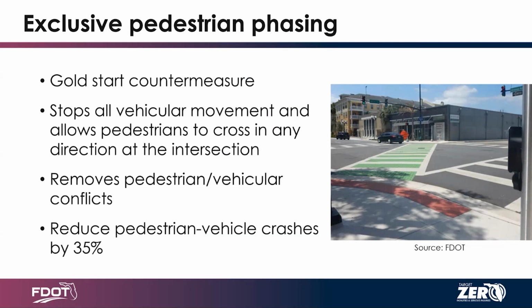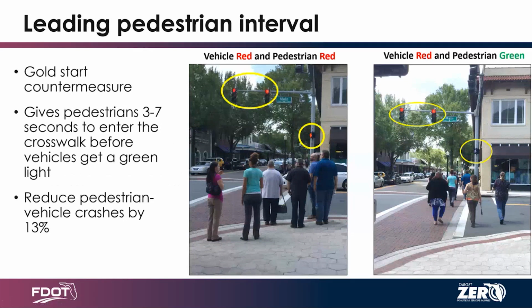Oh, Ben, I see you have your hand raised. Yeah, on the previous one, the leading pedestrian interval, does this indicate that there's any increase in rear end crashes when it's installed, or is it pretty benign in that regard? I guess the short answer is I don't know. I see Nathan shaking his head no. And so traffic's already stopped when the LPI is going. Right. So yes, there shouldn't be any increases in rear ends.